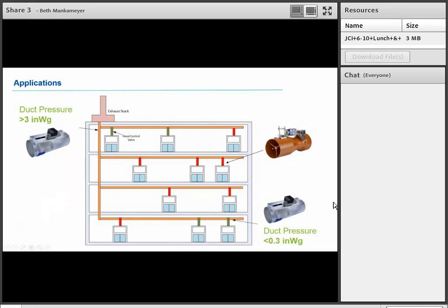And so here's another situation just showing mixing and matching where your duct pressure, so here's an example of an exhaust fan. So obviously your pressure is going to be greater closer to the exhaust fan. So these trunks with green on them are for a valve that has a wider operating range than a Venturi valve. So if it goes above 3 inches, and then in the lower end where the pressure is very low down here, the furthest away from the exhaust fan, you might need to use the measured airflow valve for the critical space down here. And then in between you can use Venturi valves. So it's one of those things where you definitely can mix and match within a system.